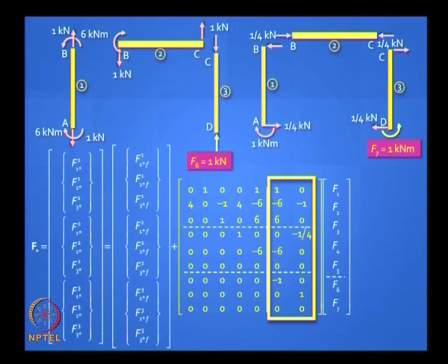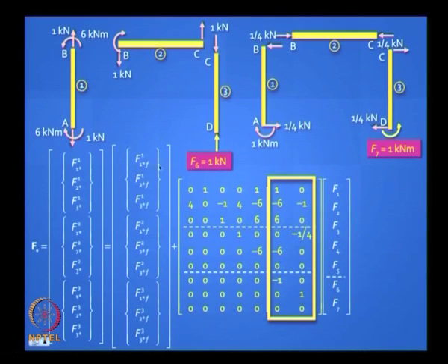These are simple things, this is a statically determinate system, you can write down those forces, but it is fun writing down the TF matrix. Now just look at this complete matrix. What we are saying is, we have written a set of equilibrium equations. If someone gives us this vector, which is the fixed end force vector, someone gives us this load vector including the redundants, we have drawn it for a primary structure. The redundants are treated as loads on the primary structure. F6 and F7 are loads on the primary structure. Is it clear? We get the bar force, get the member end forces, and we will do this in the last step. Okay, so how do we proceed now?